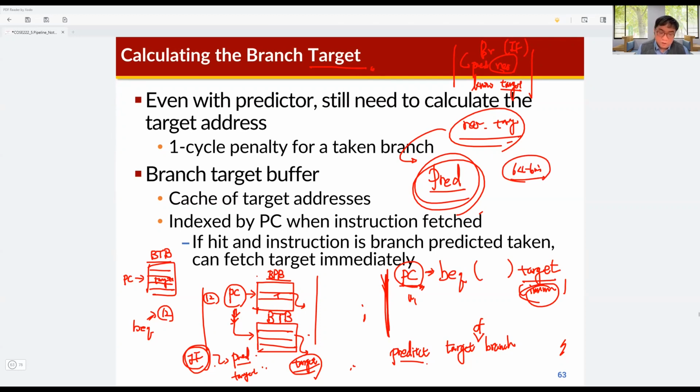For this branch prediction buffer, we can use only part of the PC, like 16 bits or even 12 bits of the PC of this branch instruction. Also, for the RISC-V, there is PC+4, so we can drop the LSB 2 bits for the instruction. So I mean we just use part of the PC address of the branch instruction for BPB or BTB. Okay.